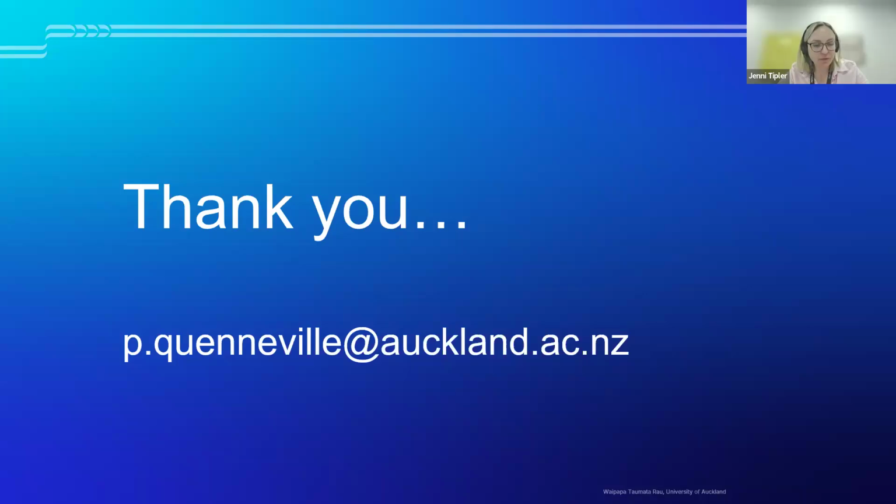So you talked a bit before about trigonometry. So I'll jump to this question. It seems like a lot of calculations and design effort for even the most basic timber connections, particularly for smaller projects. Is there not some simple requirements that can be provided for the connections to be robust? Well, definitely the easiest is to transfer forces through bearing. That's probably the easiest one. But it all depends on the requirements, the architectural requirements.